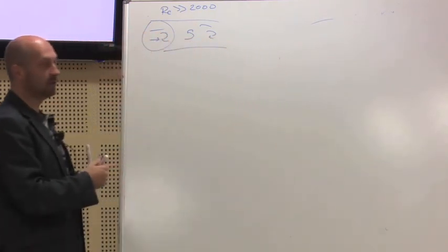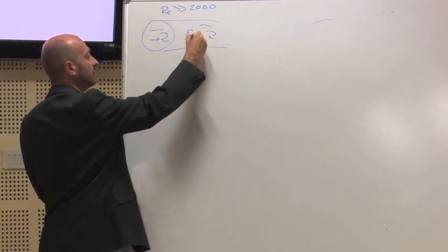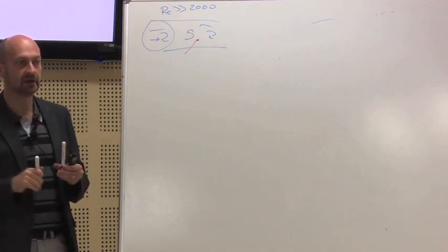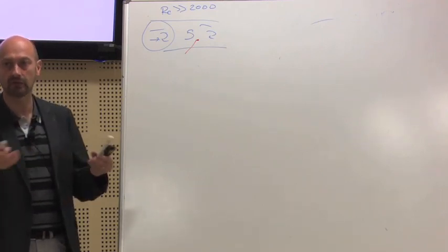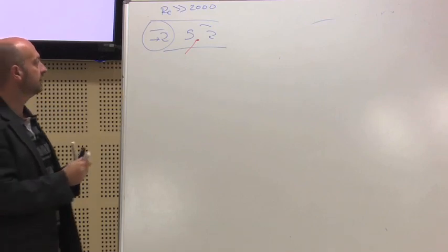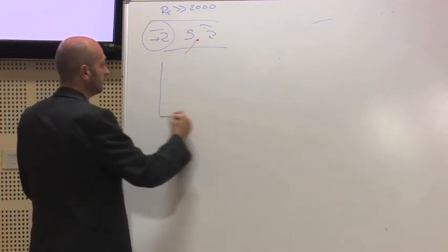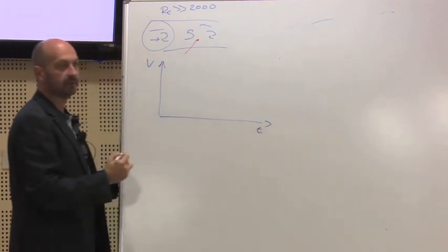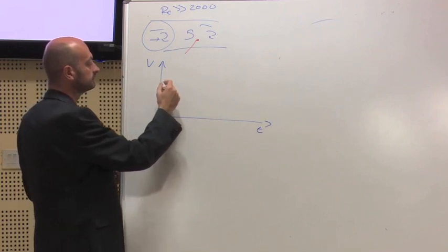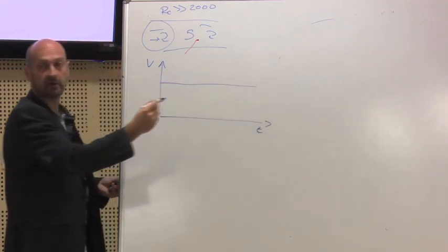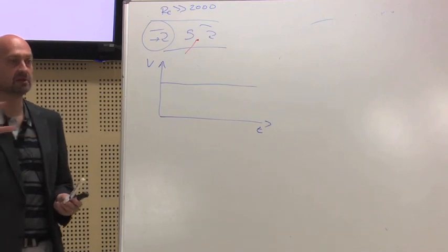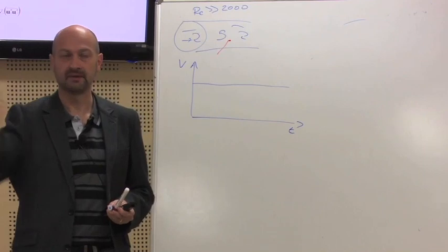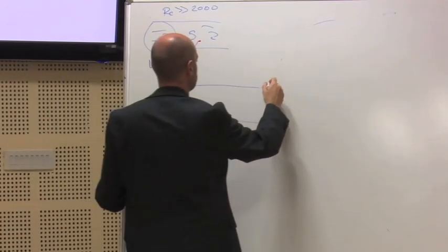Now let's assume that you have a velocity probe somewhere, so you are able to measure the velocity intensity at some point. This afternoon I will explain how you can do that with some experimental equipment. You measure the velocity as a function of time. If the flow is laminar, in a Poiseuille flow the flow is steady, so the velocity measured by the probe will be constant in time. This is for laminar flow.